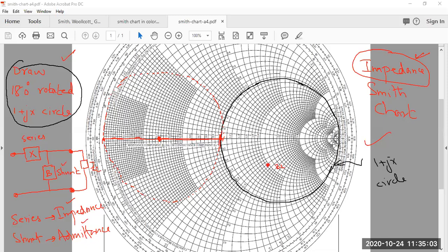So you need to consider the circuit, and you need to consider the Smith chart as well. With respect to the circuit, I am at the load position, and with respect to the Smith chart, this is the location of ZL. And now you can see that in the L network number one that we have selected for our problem, the element is connected in shunt configuration.